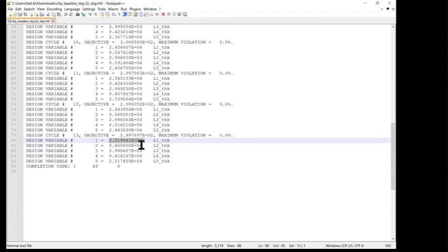So what we need to do now is change our variables to make them discrete variables so that we can choose from 0.2 millimeters, 0.4 millimeters, 0.6 millimeters, 0.8 millimeters, or 1 millimeter, i.e. we could have 1 ply or 2 plies or 3 plies or 4 plies, etc. But we can't have just over 1 1/4 plies. Clearly we're not able to manufacture that. So what we're going to have to do now is go in and change our variables from those real numbers to discrete numbers.